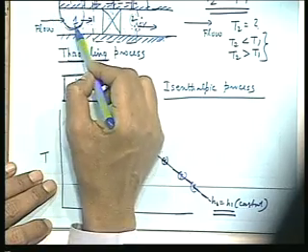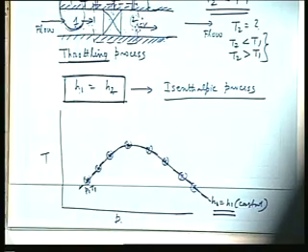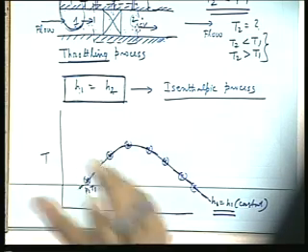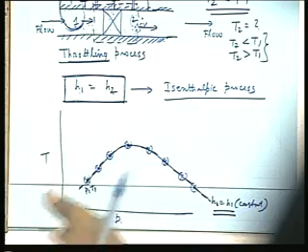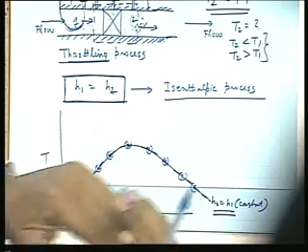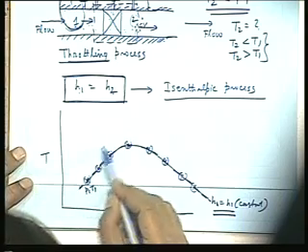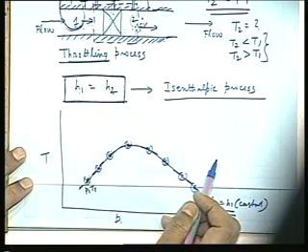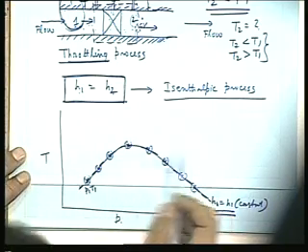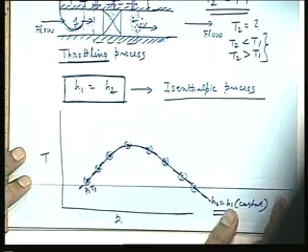That means we are going to a different enthalpy. Again at that initial condition we can throttle to different pressures and temperatures and generate different sets of P and T values corresponding to this initial enthalpy. This way we can generate a family of curves which represent constant enthalpy in the TP plane.